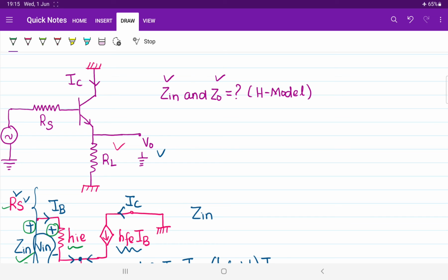See, whenever you are estimating the value of output impedance, first identify the load terminal. Just apply Thevenin theorem. Identify the load terminal, remove the load resistance from the load terminal, then connect the external voltage source VDC and assume that VDC is supplying the current of IDC. Then try to bring the relation between VDC and IDC. Meanwhile, while applying Thevenin theorem, we have to deactivate all independent sources.